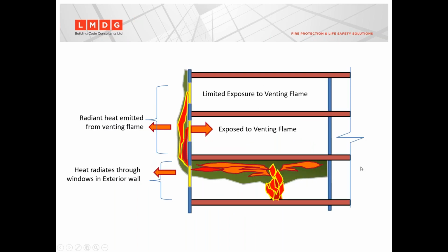And here's an explanation of the test, very similar to the NFPA 285 test for people who are more familiar with the American version. The idea of these large-scale tests, whether they're the S134 in Canada or the NFPA 285 in America, is to set an uncontrolled fire or simulate an uncontrolled fire in a lower room, which is going to burst out of a window in that wall, and the flame front is going to travel up the wall.